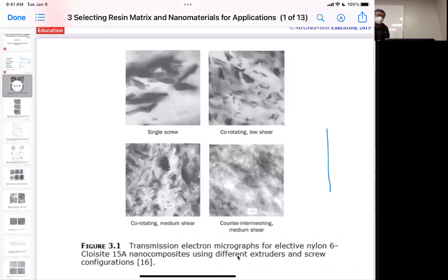Why do I say how you want to use it? If you want to use this as a modifier on a silicon chip, like a high voltage silicon carbide resistor, you don't need very much of it. You can process it in solution, or by some very expensive process. But let's say you wanted to make your nylon flak jacket EM shielding, and you want to incorporate carbon nanotubes. Are you going to do that with a solution process? No, you're going to do it through extrusion or some high bulk volume process.